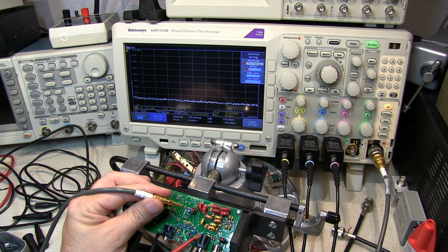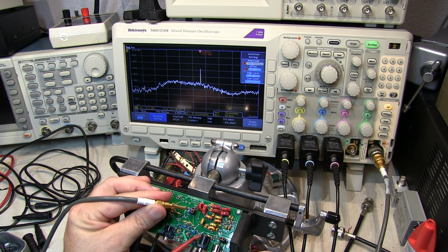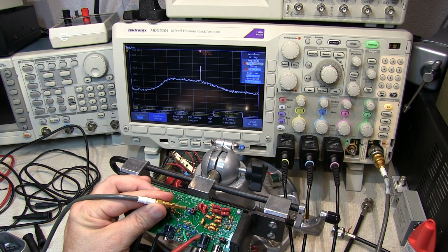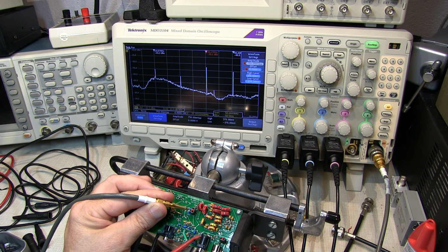So right now, if I touch the probe down here, we're looking at the bandpass characteristic for the high-pass filter, the highest frequency filter, which is the 16 to 30 megahertz filter. We're looking at a span from a little above DC out to 50 megahertz. If I look down at the next band, that one should cover from 8 to 16 megahertz. You can see that filter shape change there, and I start to see the various clock harmonics, and I kind of expect to see that.